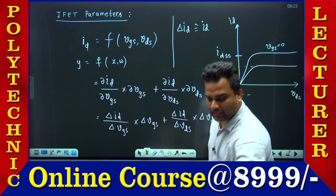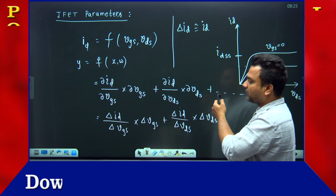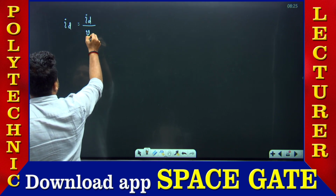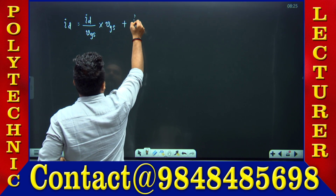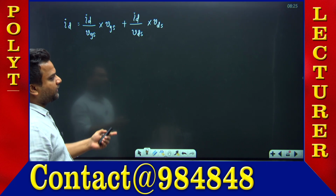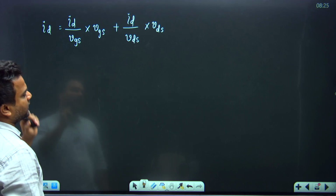So if you take del ID as ID, del VGS as VGS, del VDS as VDS, the expression can be written as ID is equal to ID by VGS into VGS plus ID by VDS into VDS. See this one, del ID can be written as ID, similarly del VGS and del VDS.